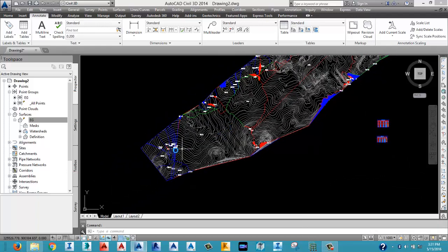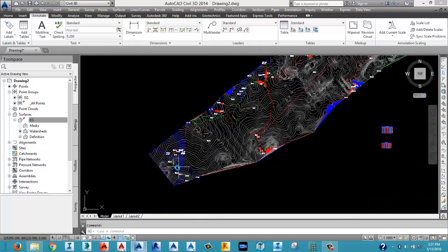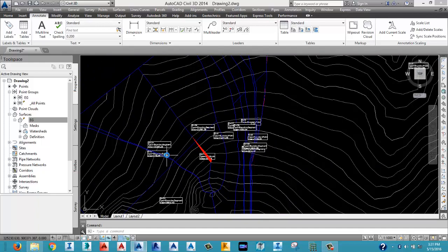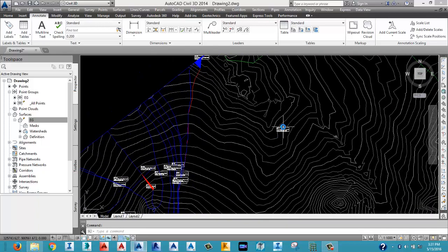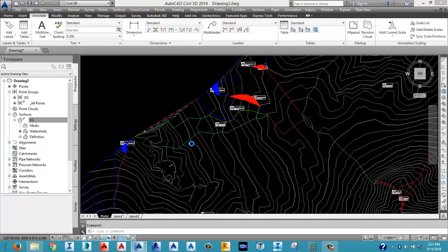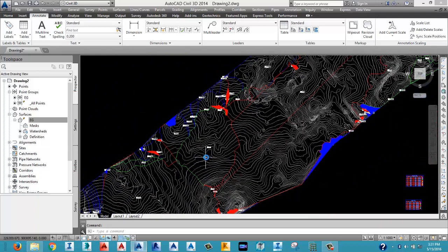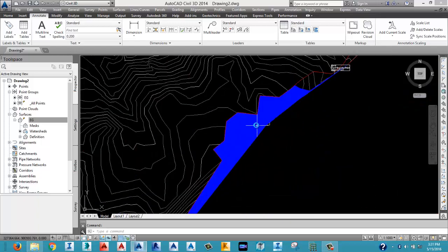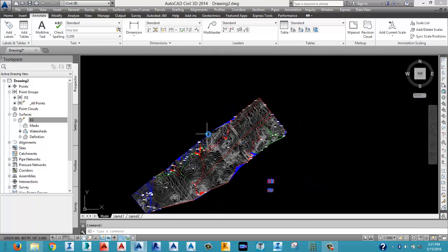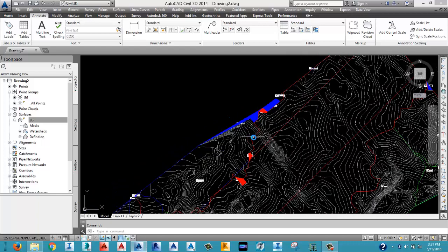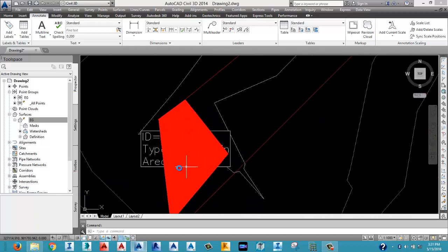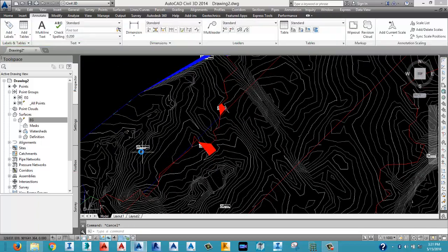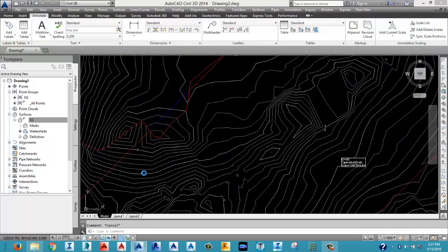So you can see what we have here. Go check what they have on this layout now. This gives you the watershed analysis, giving us the direction of flow, possible area that will be water accumulation. Those are the places you have those blue shades, and then where you have the red, those are the places where you have depressions. Everything is being boundary segments.